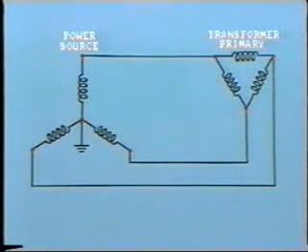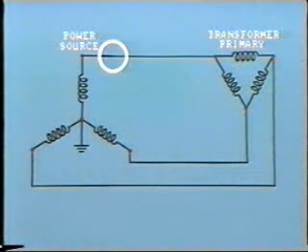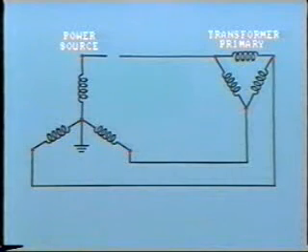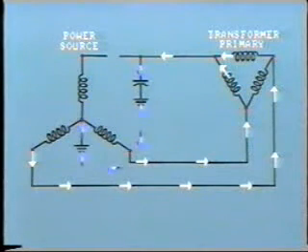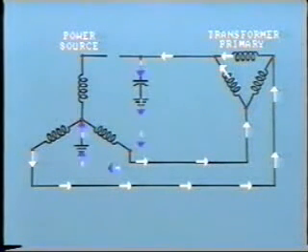As this is a distribution line, fuses are often used, so let's consider the situation where one fuse only blows, such that we have one phase open-circuited. This situation can also occur where the lineman opens feeder switches one phase at a time. In the interim period, the transformer is still connected to the other two phases, and currents will circulate in this manner. The return path to ground is through the capacitance of the open line.